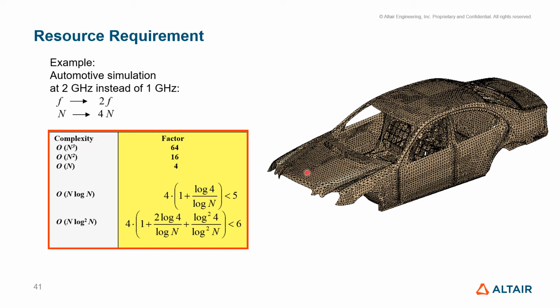What it means is that let's say you have a structure like what I'm showing here, and you discretize this for 1 gigahertz for the sake of argument. If it resulted in n triangles or n unknowns, if you double the frequency to 2 gigahertz, the number of unknowns will be 4 times n. That is because of the surface.